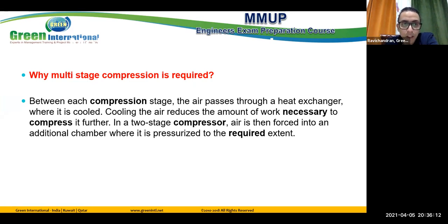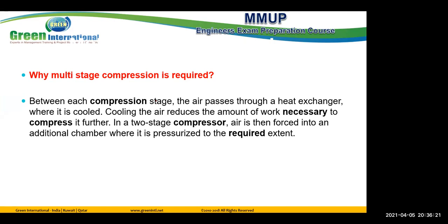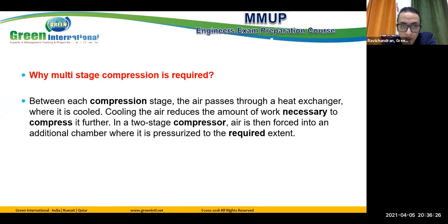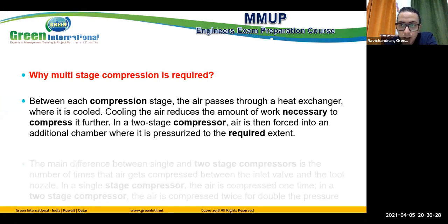We will see later. Multi-stage compression. Here, between each compression stage, the air passes through the heat exchanger where it is cooled. Cooling the air reduces the amount of work necessary to compress. So let's see here in the curve what happened.